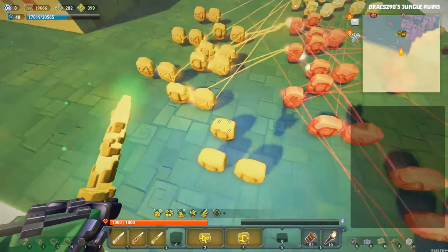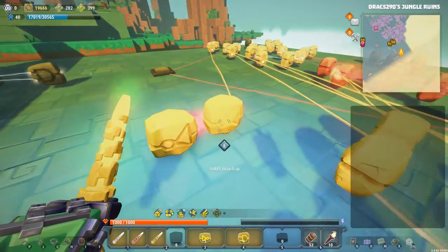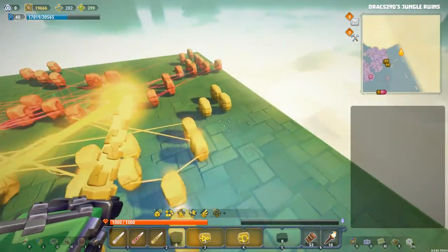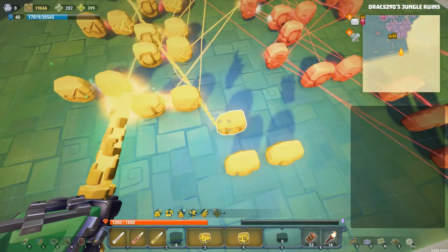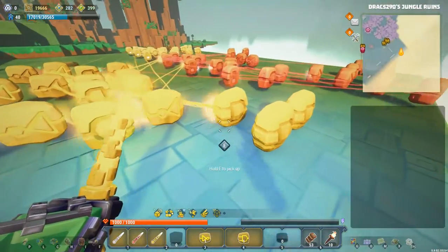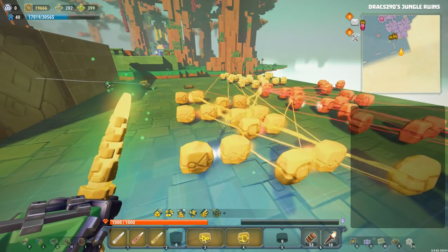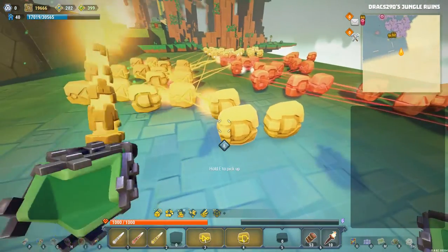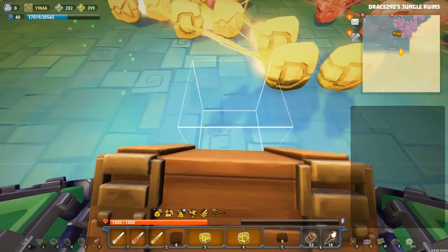So the first thing we want to do is, before I go and make this extra NOT gate that I missed out on, we're going to want to hook all of the NOT gates from the latches, from the nodes here, into one of the sides of an AND gate. So the first one goes into the A of the first AND gate. The second one goes into the B, right here, of the first AND gate. The third one down the line goes into the A of the second AND gate. And then I'm going to place down the NOT gate that I have here.